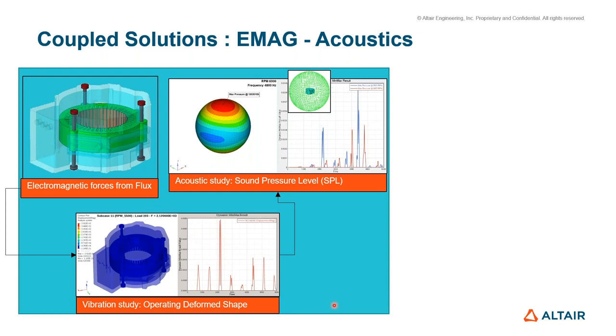It's complex in terms of electromagnetic and acoustics, but SimLab gives us a platform to efficiently make sure the pretension bolts are applied on these motors, getting those electromagnetic forces as excitation points from the structural point of view to conduct harmonics analysis. Then we would look at various speeds and also measure sound pressure levels at